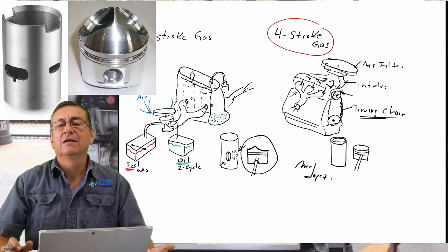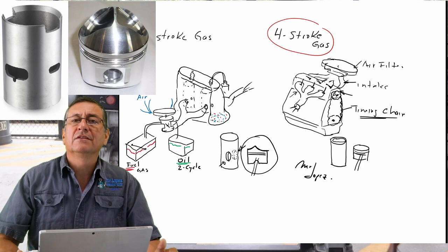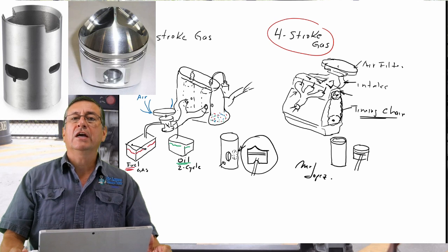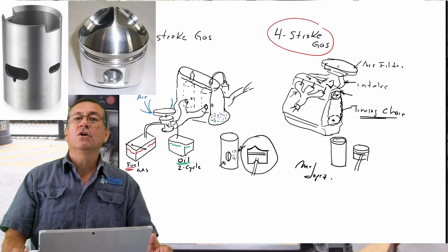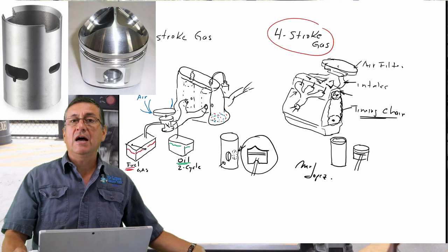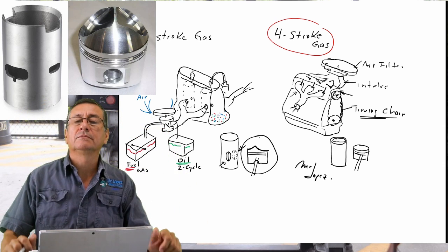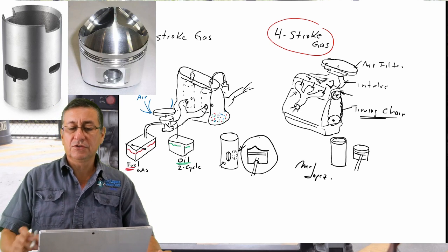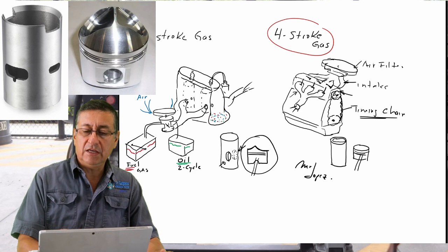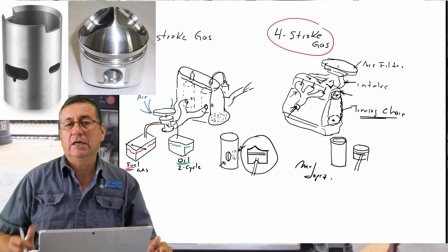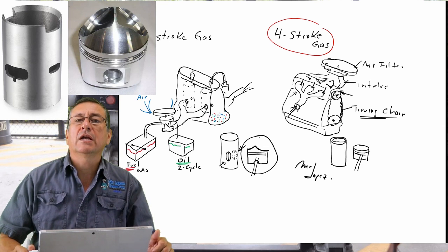Yeah, one of the differences. If you check by visual inspection, the two-stroke engines have the input of the mixture and the output of the gases in the bottom of the block, not on top. In four-stroke engines, the intake and the exhaust manifolds are located on the head, in each side of the head, like the picture that you have on the screen right now.